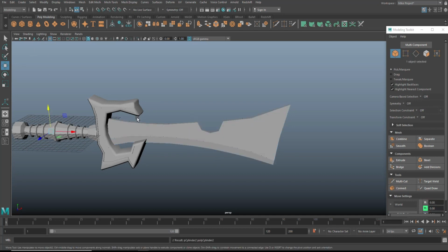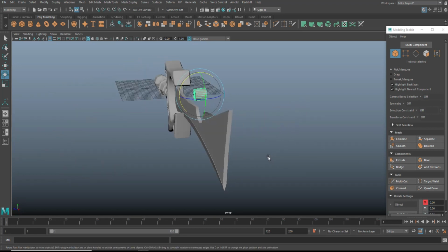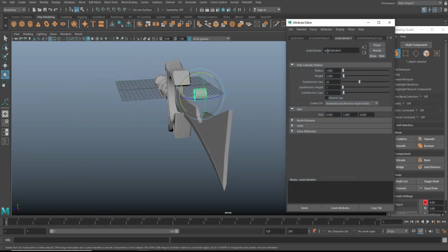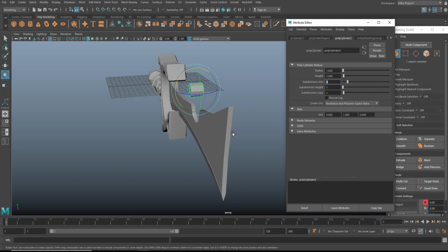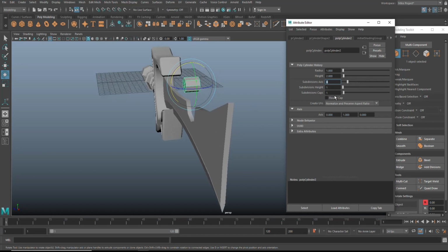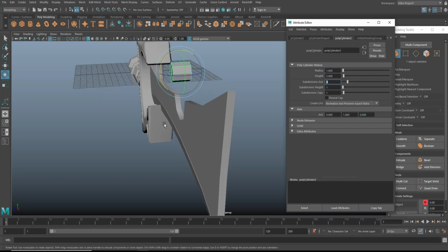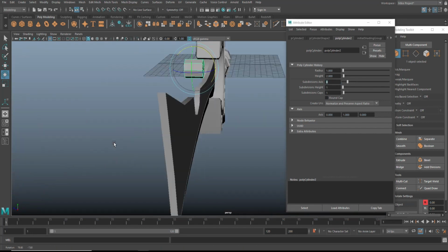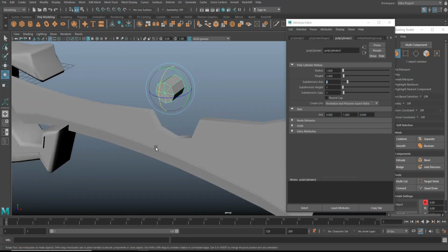So then we want to have that thingy, yeah. And for that, we'll take a new cylinder, and we'll move that up, and we'll hit E to rotate, and then we'll flip it down like this. Yeah. We're going to Control A to open up the attribute editor. Let's set this to 8, so it should fit in here just the way it should. We don't have any n-gons right now. We've got triangles in the front and back, which is all right.